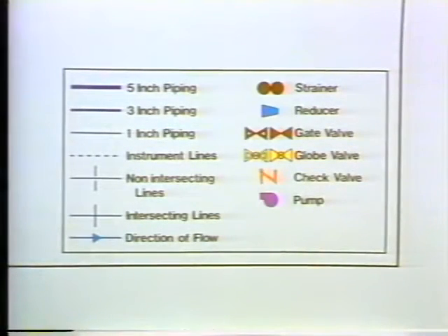Because there's no one set of standard symbols used, manufacturers and plants have to provide a chart indicating the language that they use on their prints. It's very important that you find and use this chart or legend whenever you read a print. Usually, a manufacturer will use a standard set of symbols throughout his prints, and a plant will use a standard set throughout its prints. When you have found the correct legend for a print, you can then read that print.